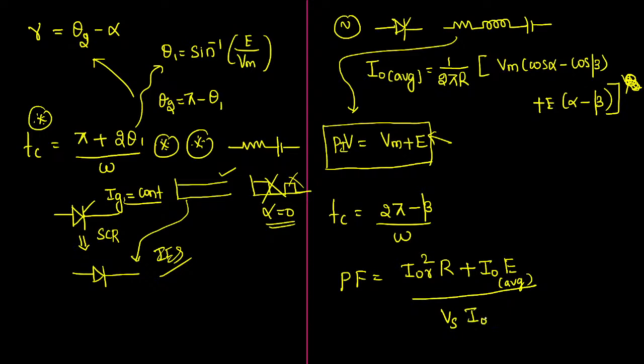Here input RMS current and output RMS current are the same, you can directly substitute. Remember, when you calculate the power dissipated across the resistor, you must use output RMS current. It will be directly given in your examination. Whereas to calculate the average power, you must calculate the value of I naught average. You know the formula, I have just defined it. After calculating these two, substitute here in order to know the value of power factor offered by the circuit.